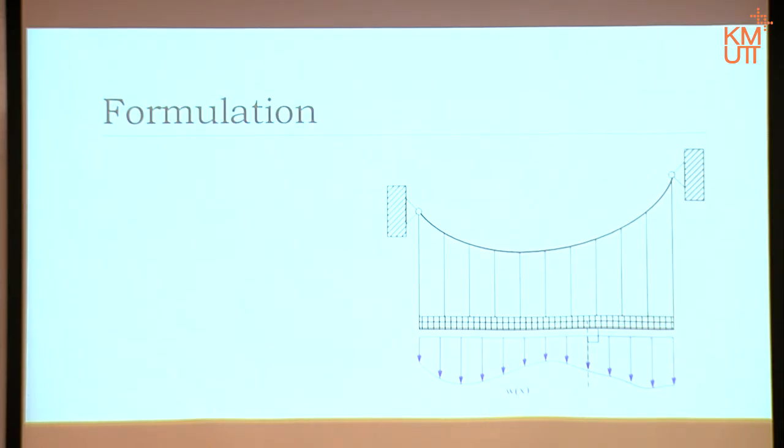So when we calculate this cable, we look at it as if this distributed load at the bottom, which will include the weight of the load itself as well, goes straight to the main cable up here. Now, before we start, when we start designing it, we don't know the shape of this cable.